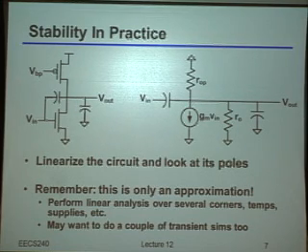Okay? And the implication of remembering that it's really only an approximation is that you can't just do one linear analysis. You can't just say, well, my circuit is always here, I'll analyze exactly that situation, and if it's good there, I know it's good. Not true. All right? You actually have to check it over all of the weird conditions that might ever pop up. Okay? So in particular, you should check it across different process corners. You should check it across different temperatures. In fact, I even argue you should check it across different power supplies.